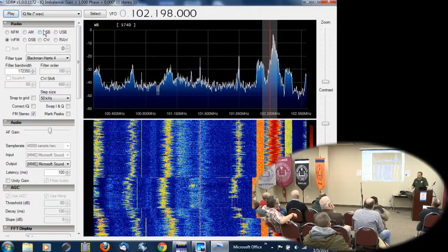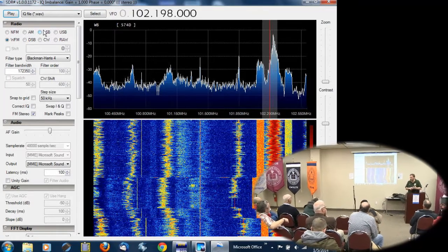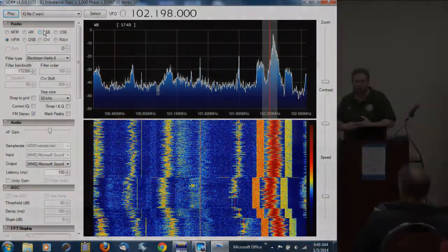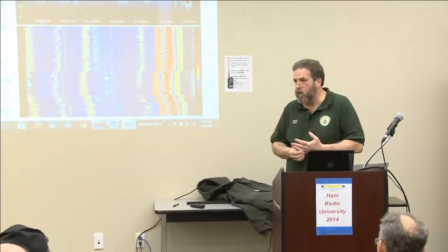So there's tons of different software out there. One of the things I like is the PowerSDR software. For whatever reason, the filtering written for that works really well. It's open source. There's different versions out there available. There's PowerSDR IF that's been written that I use with the 940. There's PowerSDR IQ that works with the SoftRocks and some other radios. Again, it's software. It's what you want to do with the radio and what mode you operate. If you're a sideband guy and you do a lot of contesting, you can't beat SDR for what you can see and how you can control the signals.